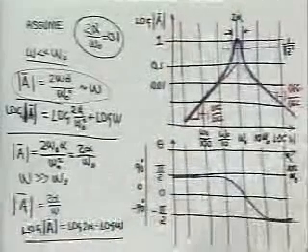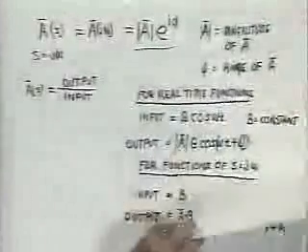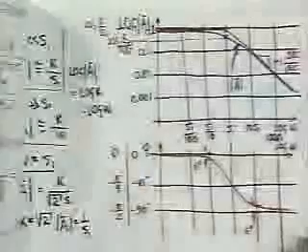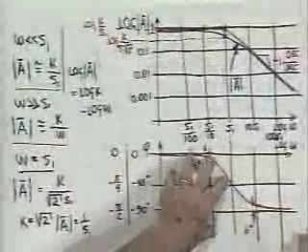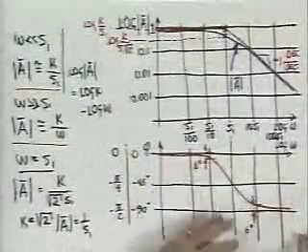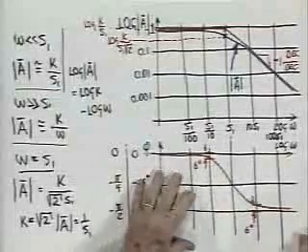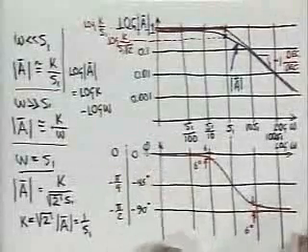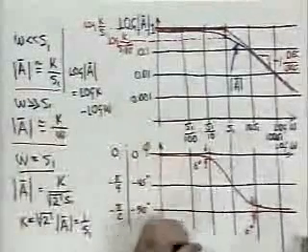All right, we've seen how the Bode diagram can be plotted on the log-log coordinates for magnitude, semi-log coordinates for angle. The only thing that's involved here is to find the high frequency and low frequency asymptotes, for which case you approximate the magnitude of the transfer function. In this case, we had what was in effect a low-pass filter.